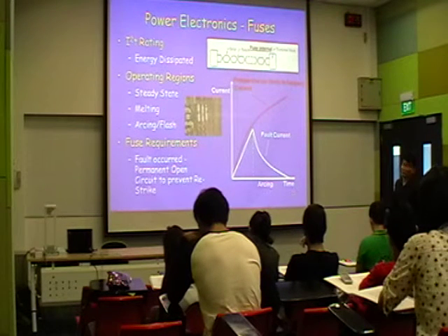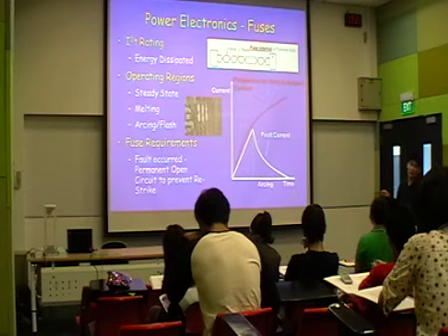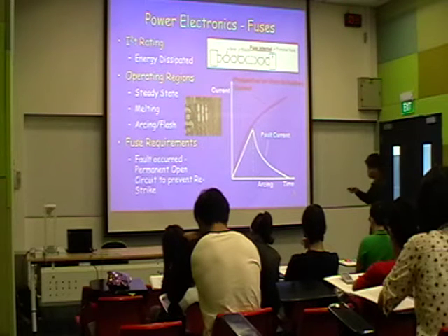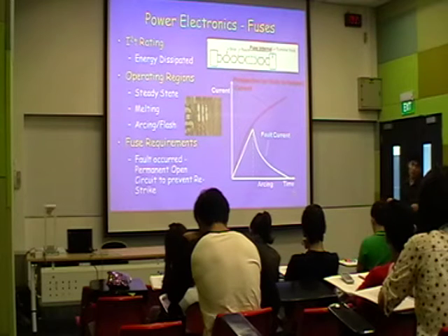If the cable is exposed and the exposed cable is on the ground, then when someone touches it, they experience very high current, but it will be discharged down to the earth. So sometimes you talk about the exposure time of the short circuit. The time frame is also quite important.